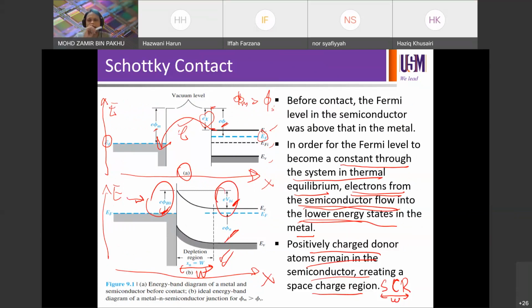And another barrier height is the barrier height in the semiconductor, QVBI, seen by the carriers in the semiconductor, preventing them from flowing. Like a wall here, stopping them from flowing, and you have another wall on the left, stopping them from flowing as well. So remember, we have two barrier heights, not a single barrier height.